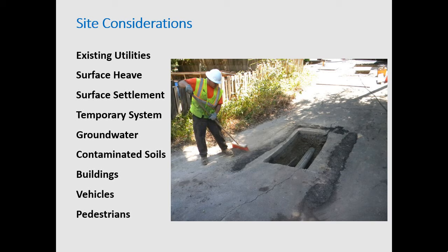Surface heave. It's really good to estimate that surface heave. Now the new manual doesn't have the same equations that used to be out there. They realized those equations were too conservative. I talked to one of the authors about it, and they've got this zone of influence, and it all depends on how much of an upsize you're doing.